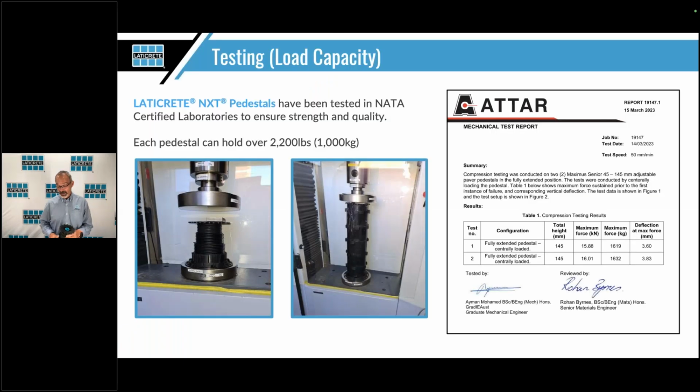Testing and load, as far as I know and understand, there really isn't a number out there that's, hey, you have to meet this. Ours, we're telling you it's 2,200 pounds. It surpasses that, but we're going to tell you it's rated at 2,200 pounds. We're going to remind you that the pedestal is not going to be your problem. The problem is going to be the material between. What is the manufacturer of your finished goods? What's it rated at, and how is that system going to work?